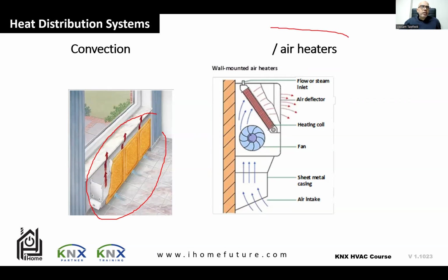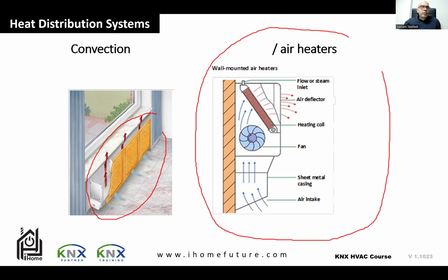Or you have an air heater, which is used mostly in bigger areas because it's a bit loud. Then you have a heater and a fan pumping air to the heater, so you are getting the hot air in your house. So air heaters are primarily used in large workshops, industrial installations, and storerooms. They consist of a heating coil heated using hot water or steam, and a multi-speed fan, which is pushing hot air to your area.